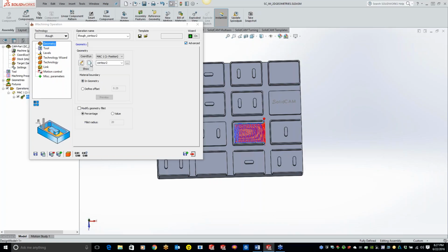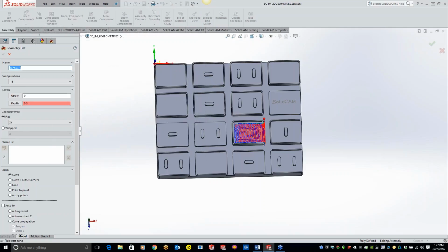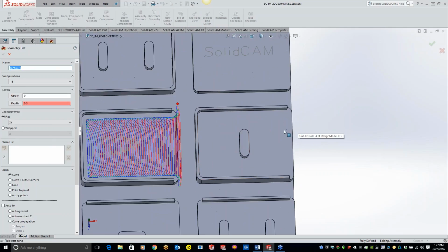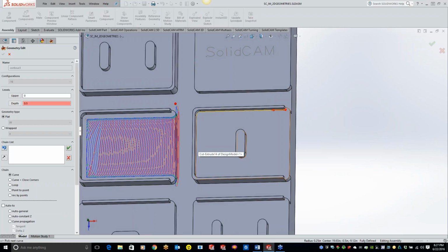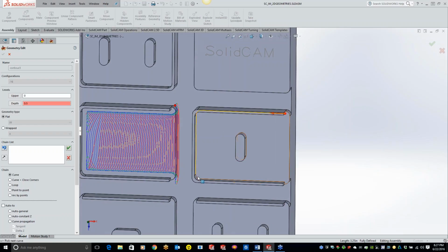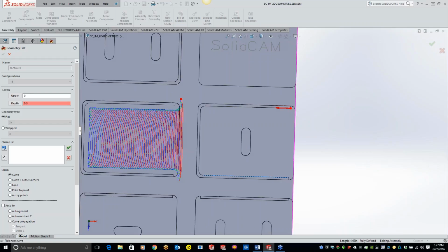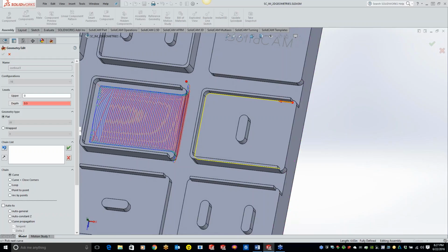So what we'll do here is the point to point. If we come over here, let's just do curve. Grab that last one here. Now, let's say you don't have any geometry there. What we can do is the point to point, like I said before, and close it off that way. Now, one thing with the point to point is the mark open edges.